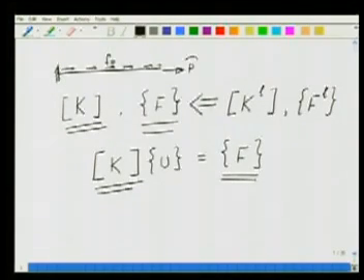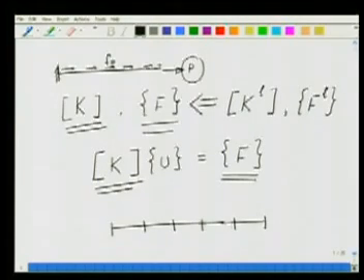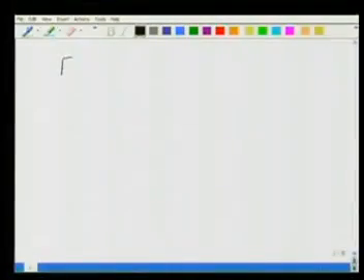We had taken care of this end force P here by saying that if we consider the domain is broken into 5 elements, 1, 2, 3, 4, 5, with nodes x1, x2, x3, x4, x5, x6, x6 is equal to L and x1 is equal to 0, then for the entry F6, we updated it equal to F6 plus P. That is, in the final entry of the vector F, we added the value of this end load P, which is applied.